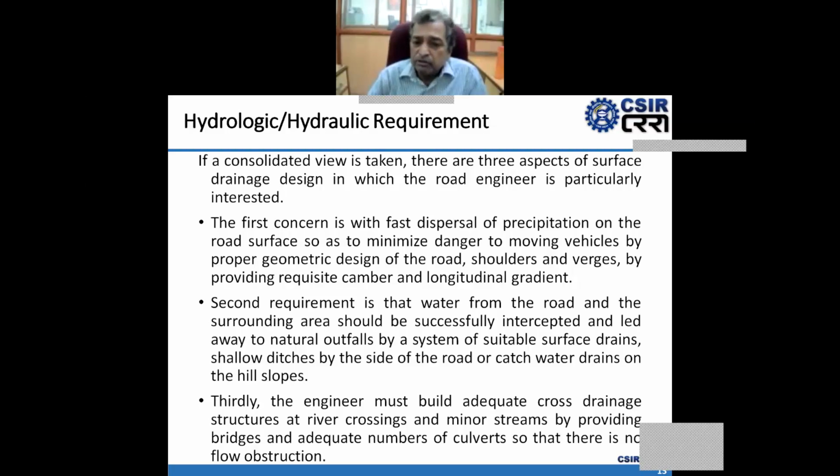Second requirement is water from the road and the surrounding area should be successfully intercepted and led away to natural outfalls by a system of suitable surface drains, shallow ditches by the side of road or catch water drains on the hill slope.